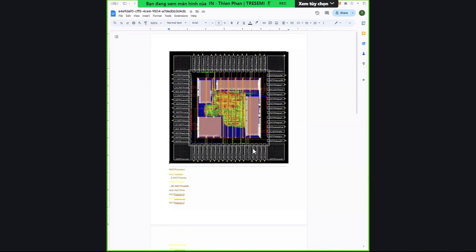If you put a halo around it, it should extend to the boundary, so there's no row. Even if you have a row, when you put a halo over it, it doesn't route M1 underneath. So if you have an M1 route there with no standard cell, it's going to be dangling, with nothing connected to it. Okay, that's a good guess. Check the halos. Let me see the halo here.